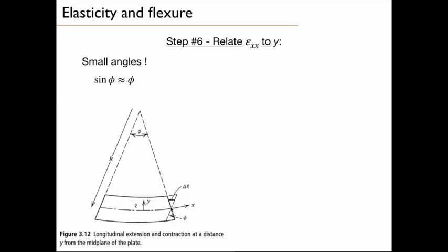And you see that this deformation varies along the thickness of the plate. So we have this radius here and this opening angle, phi. And phi can be approximated as L divided by R. Once again, L is here and R is this length. That's using the small angle approximation.